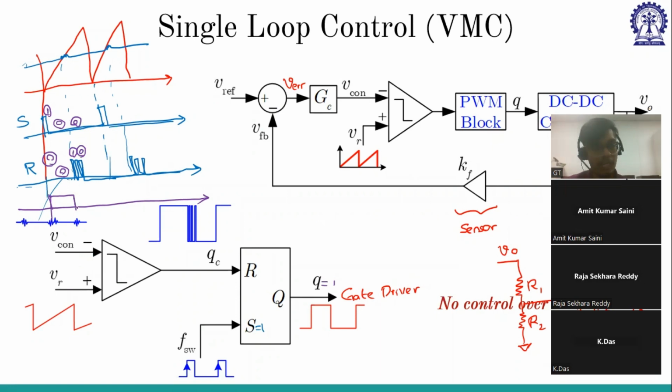So it will still retain the previous value, which is 0 because it got reset here. And again, reset has become 1. It will still be reset, and reset has become 0. It will retain the previous value 0. So even if there is noise, because it got reset once, and even if R is becoming 0, both are 0 anyway, and it will retain the previous value. So it will retain the 0 value until you get the set pulse 1.